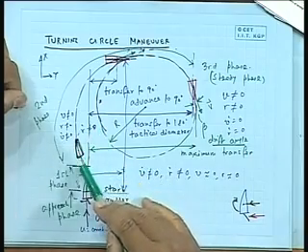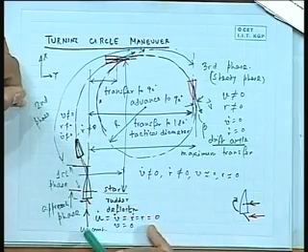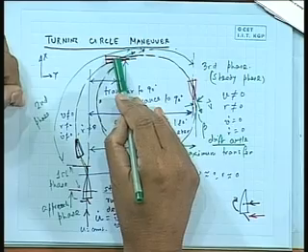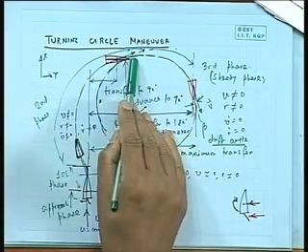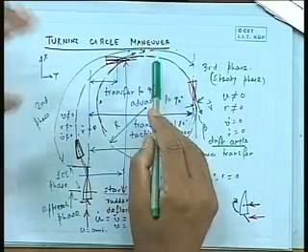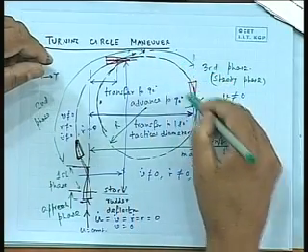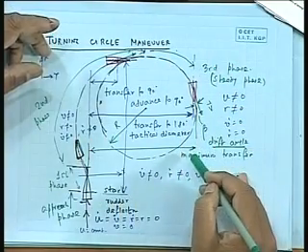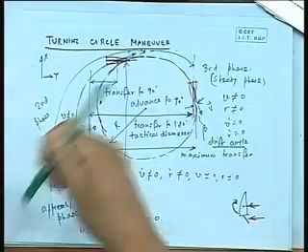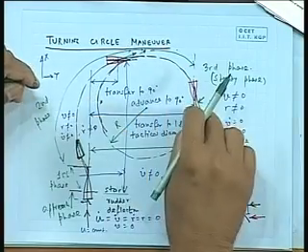Remember, of course, one thing is that one also measures the speeds, because the approach speed u has changed here because of the angle. There is an extra x force that comes, so the forward speed u also changes. But eventually that also will reach a steady state. All of them will reach a steady state, but initially there is a reduction. When you give a rudder, you are giving an extra drag force also. So obviously the speed also changes, because you are not changing the engine setting. Engine setting is fixed. Now the distance along the x axis is called advance and along the y axis is called transfer.